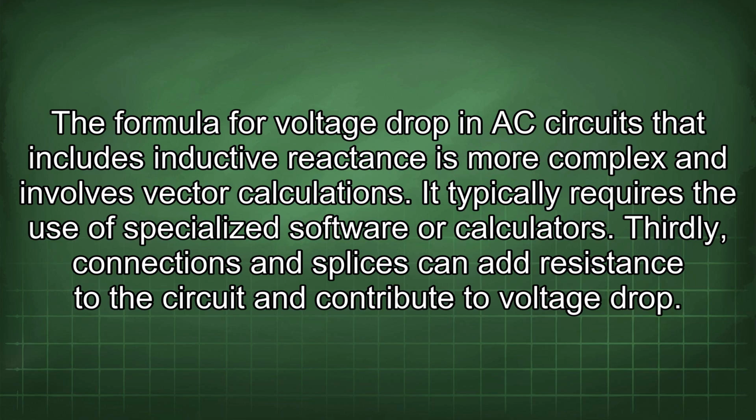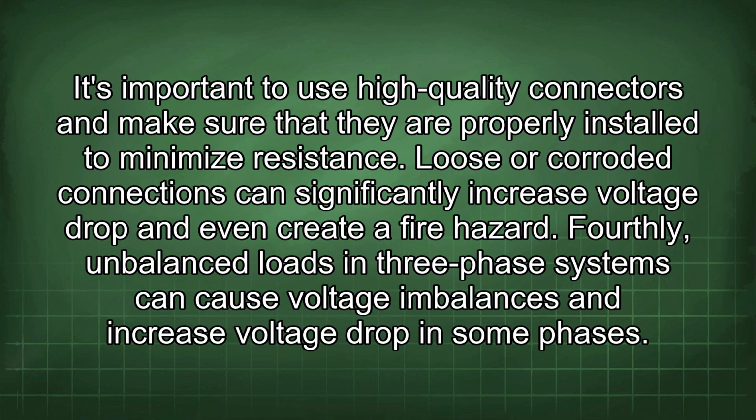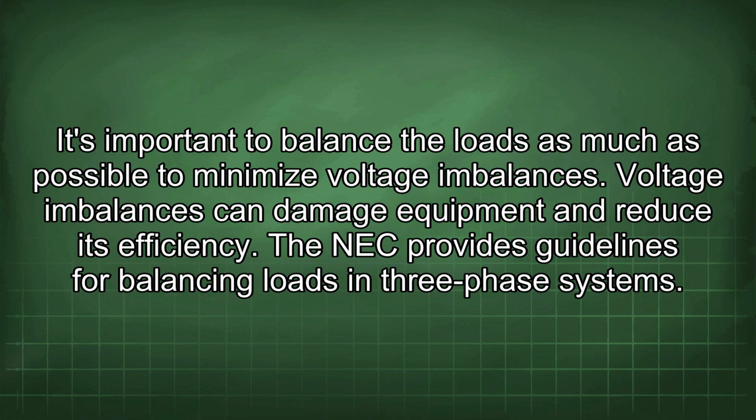Thirdly, connections and splices can add resistance to the circuit and contribute to voltage drop. It's important to use high-quality connectors and make sure that they are properly installed to minimize resistance. Loose or corroded connections can significantly increase voltage drop and even create a fire hazard. Fourthly, unbalanced loads in three-phase systems can cause voltage imbalances and increase voltage drop in some phases. It's important to balance the loads as much as possible to minimize voltage imbalances. Voltage imbalances can damage equipment and reduce its efficiency. The NEC provides guidelines for balancing loads in three-phase systems.